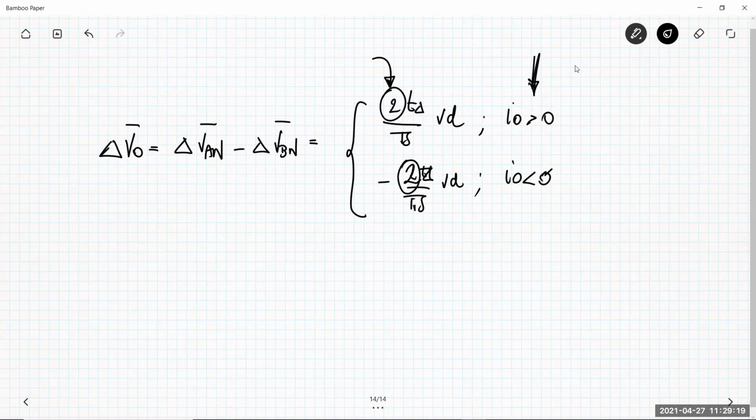Remember that the switching has a direct impact on the ripple of the torque. So in situations where your motor has a very low inertia and you are searching for something that filters out high order harmonics, the unipolar pulse width modulator can help.